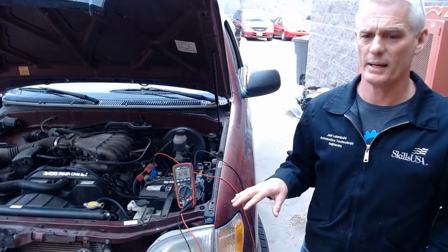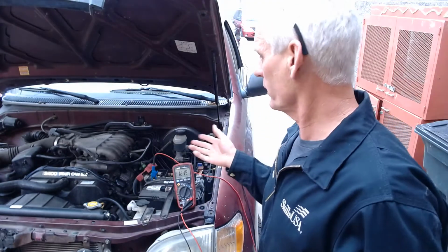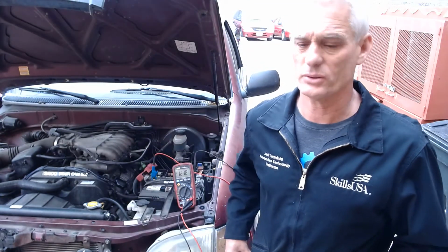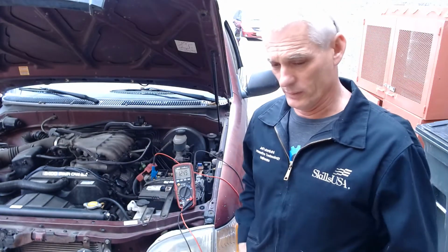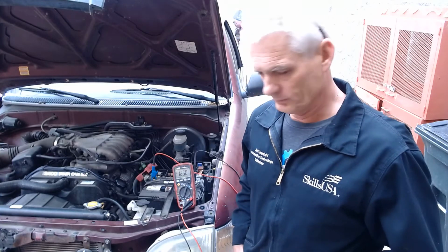So the headlight test helped us to know it wasn't the battery. And now I know that I've got to pull the starter out and fix those contacts. And so I'll probably do that and then show you the video and clip it to this one so you know how to do it. Okay, that's it for now.